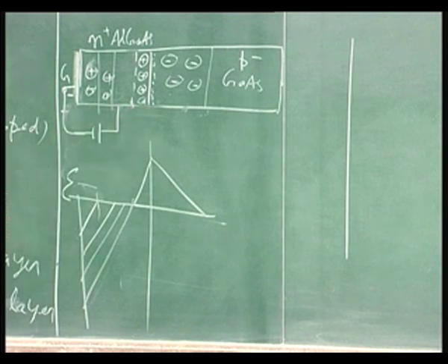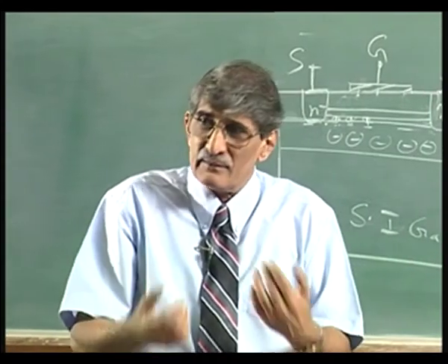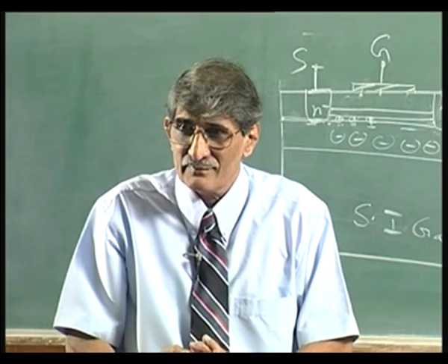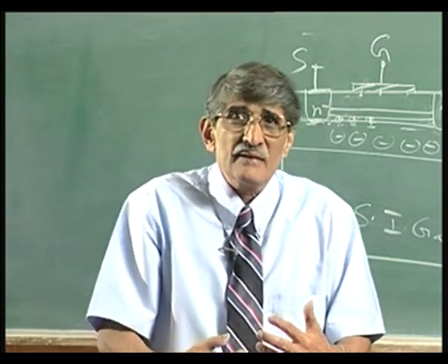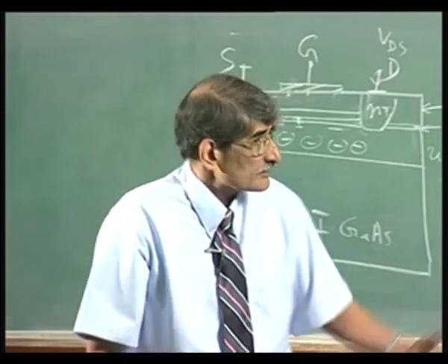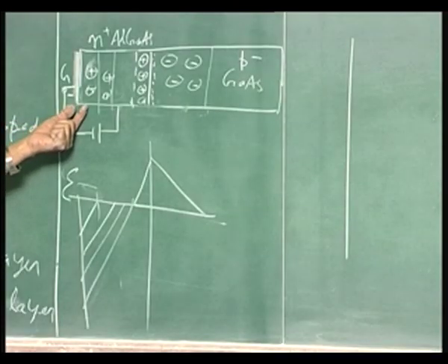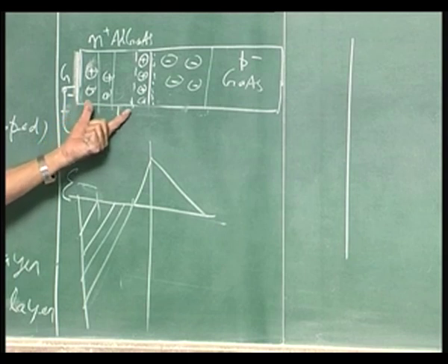See, the interesting part here is, when you apply voltage to the gate, if the VBI is lower than VP0, that is easy to understand. Depletion layer width is much smaller than A. If I want to deplete, I must apply negative voltage till that reaches and touches this point.